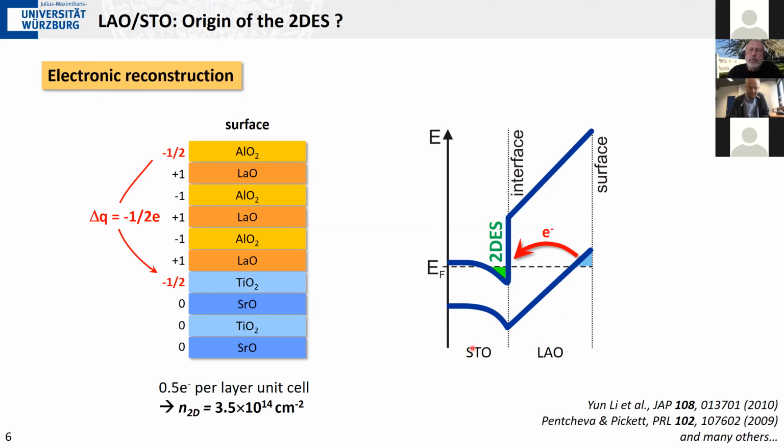And when the thickness exceeds a certain critical thickness, you can see that the valence band maximum crosses the Fermi level. These states get depopulated, and these electrons will then look for the lowest possible energy states that they can occupy, and this happens to be this potential trough at the interface. And that's then what you expect to see.